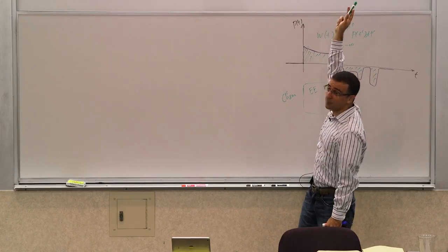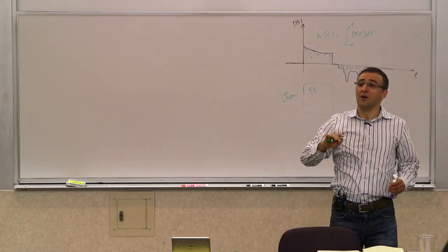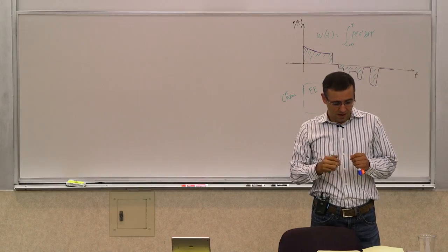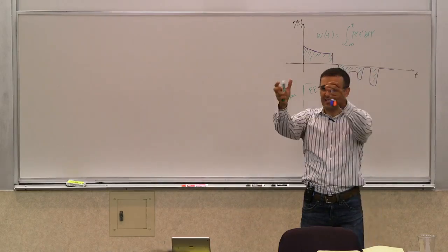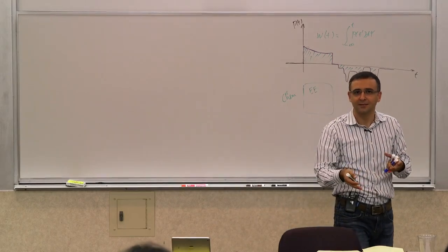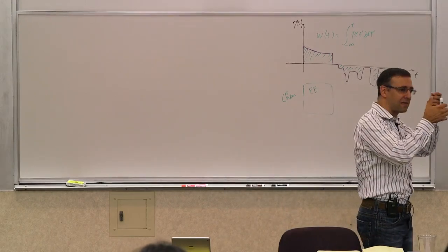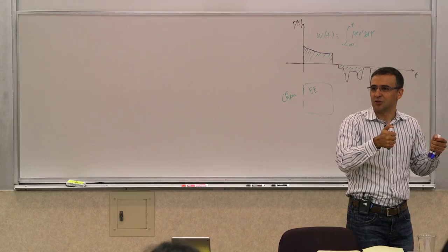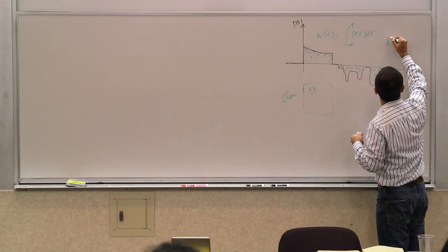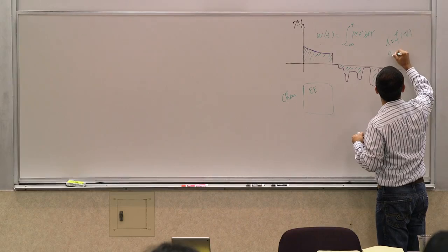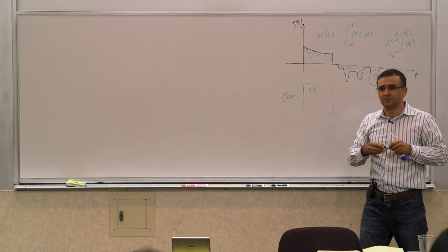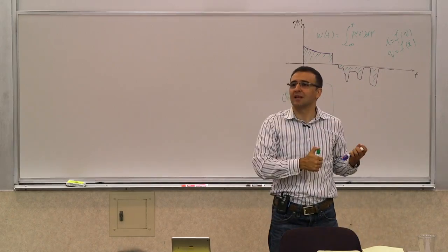So you have both negative or both positive. And that's exactly the definition of a resistor. It's a mathematical definition of a resistor. Now, as I said, there's a physical resistor, which has all sorts of complexities, and we'll talk about that a little bit in a few minutes. And there's a mathematical resistor, which is technically this relationship, which is I equals F of V, or V equals F of I. And this is an abstraction of that physical resistor.